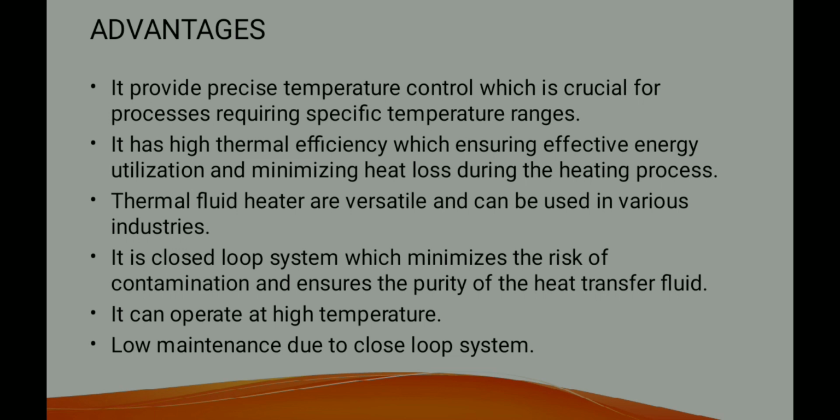It provides precise temperature control, which is crucial for a process requiring a specific temperature range. It provides a constant temperature for the process to work. It has high thermal efficiency, which ensures efficient energy utilization and minimizes heat loss during the heating process. Thermal fluid heaters are versatile and can be used in various industries. It is a closed-loop system which minimizes the risk of contamination and ensures the purity of the heat transfer fluid.